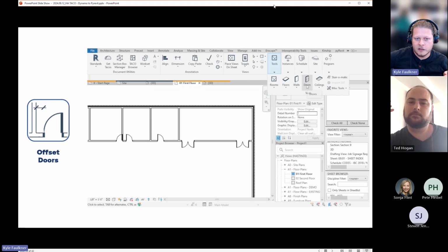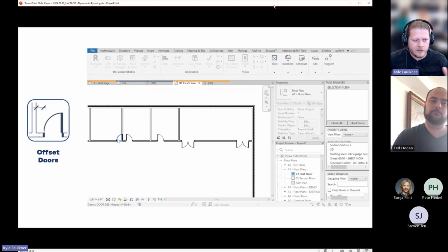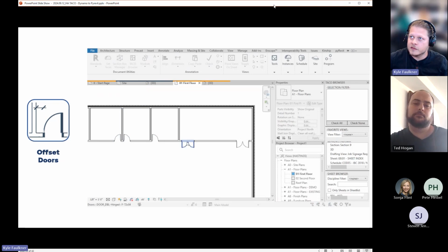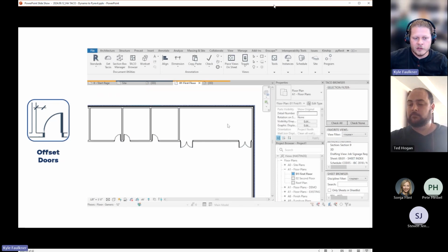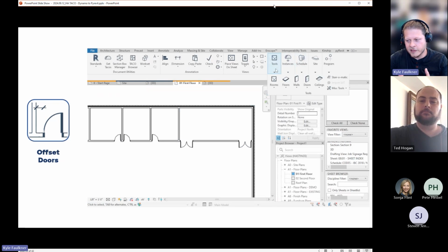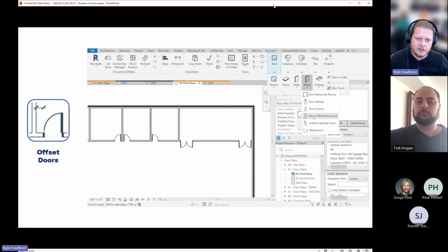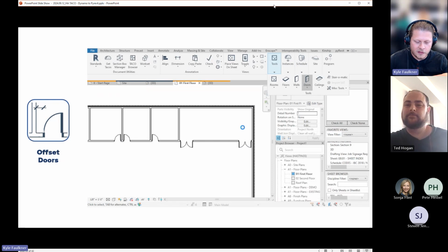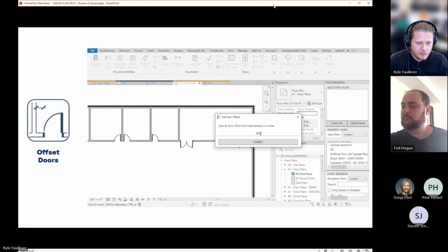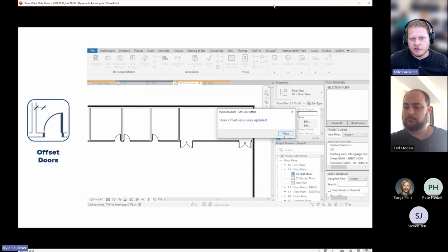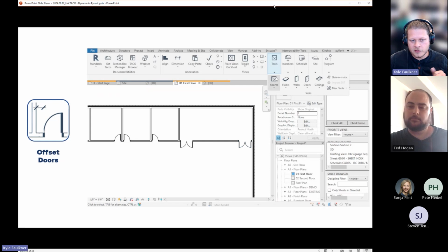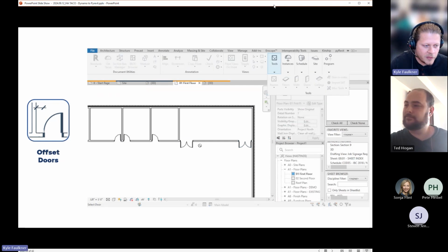We have used the shift click a lot. A lot of times we'll have tools that alter the view in some way, like our highlight misaligned walls tool. It'll change every wall in your project to pink if it's not lining up with the grid that you specify, and it would be super tedious to undo all that color changing if you're relying on that to make some changes. But if you just shift click the tool, it'll turn all that off. So it's a great function of pyRevit that really increases what you can do with the tools.